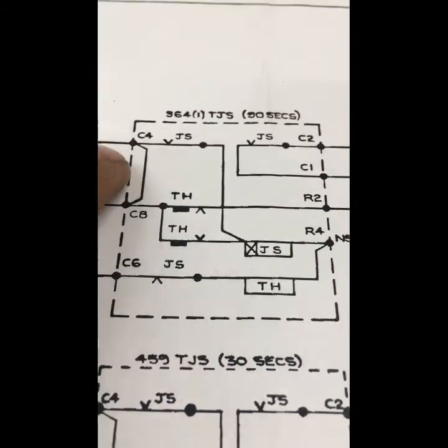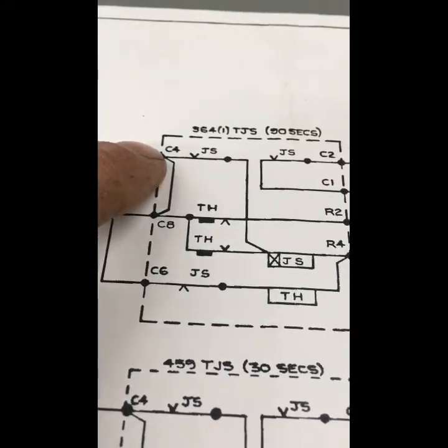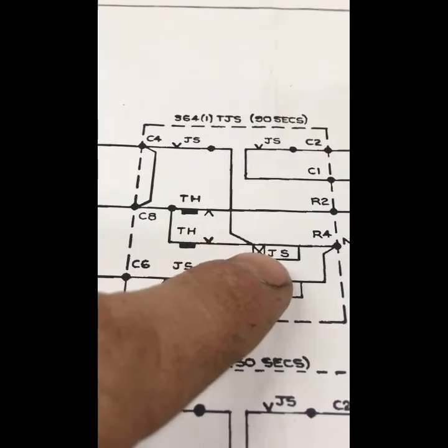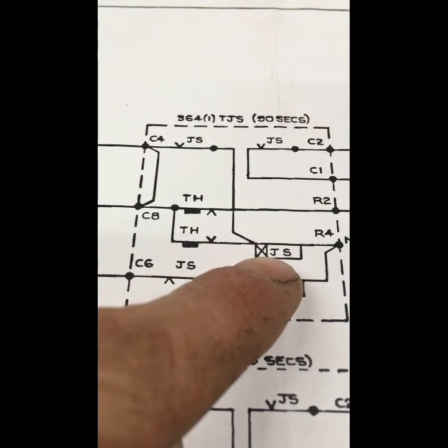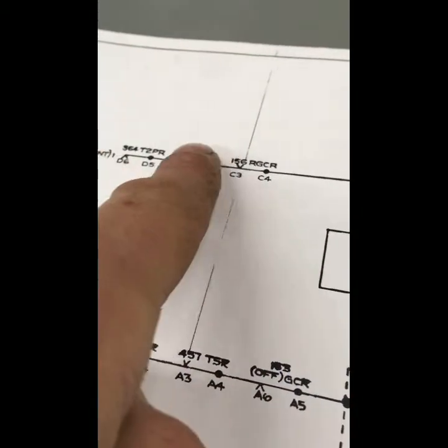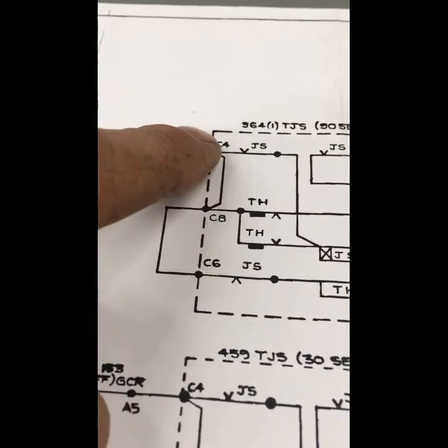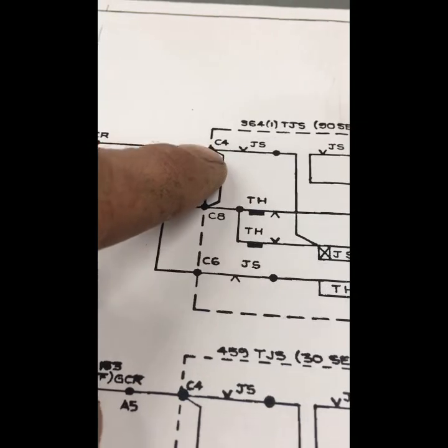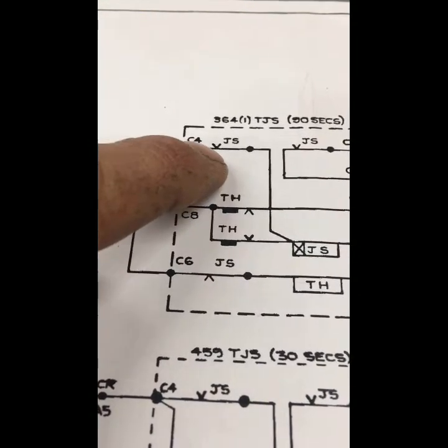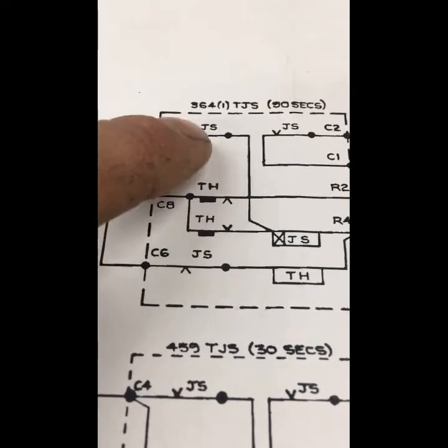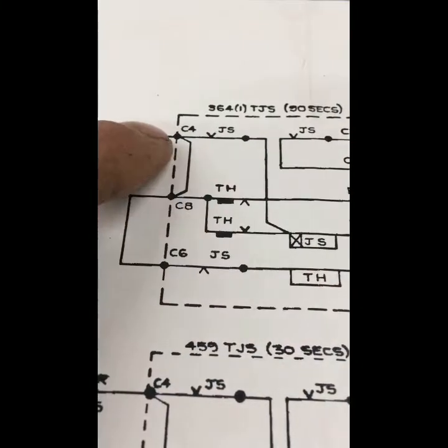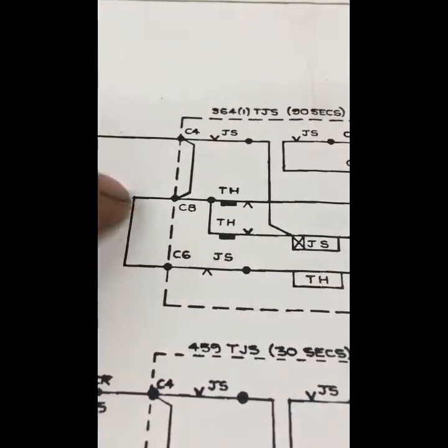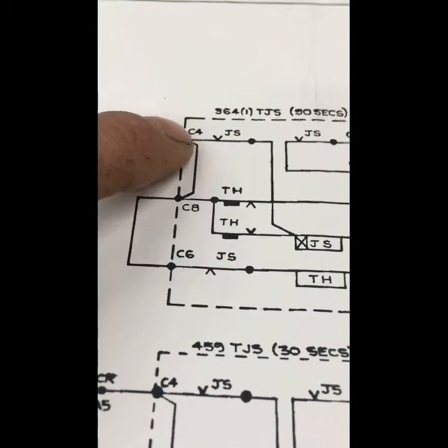So to follow this circuit through, we've mentioned we have our feed coming in here. The timed stick relay here will not be energised to start with, because our circuit wasn't fed. Now we're feeding our circuit, we flow into here. Now we've got two paths. We cannot go through this contact because this contact is down to start with. This contact, the JS, is the contact of this relay, and this relay is down to start with, because nothing has been feeding in from the left. So we can't go through that way, so we must go down.